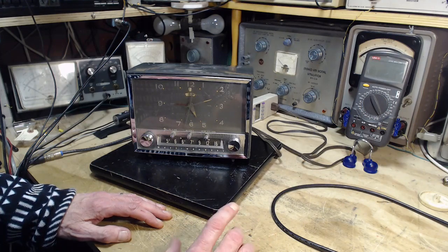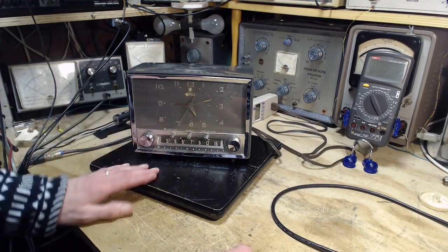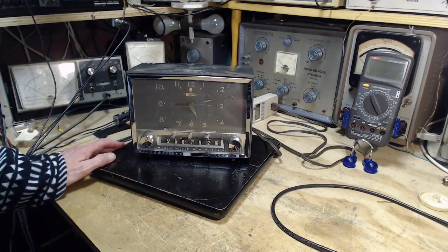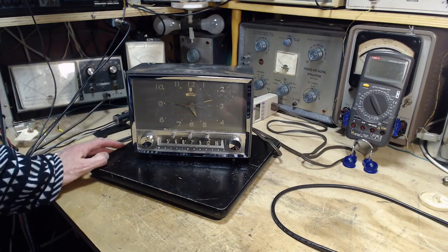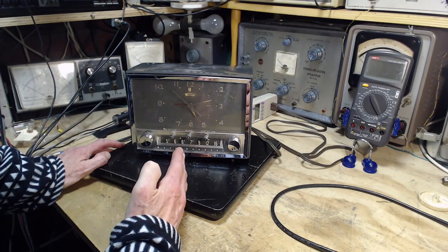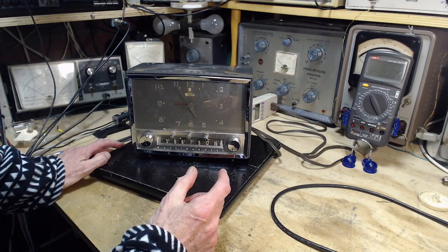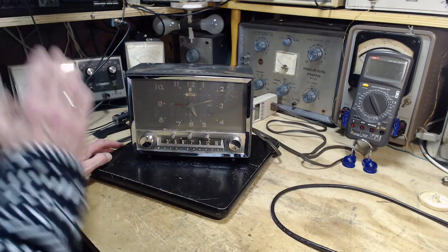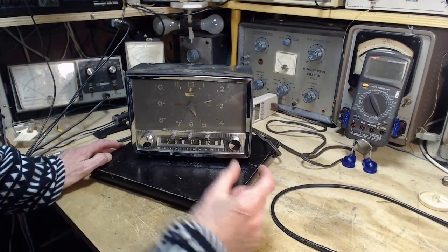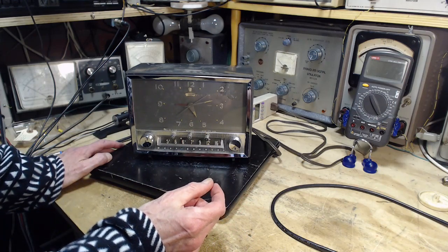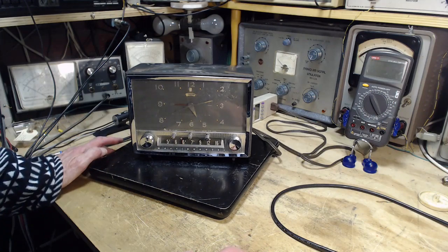When you're fiddling around with that control, it sounds a lot like this. Let me be more specific. If you have the BFO set so that its oscillation is exactly the same as the IF, when you tune in a signal, as you get it dead center, there's this heterodyne oscillation that's been set up between the BFO and the incoming IF signal you're tuning in. The separation gets less and less and less. The frequency comes down, down, down. It goes all the way down to, well, it eventually gets to essentially 0.